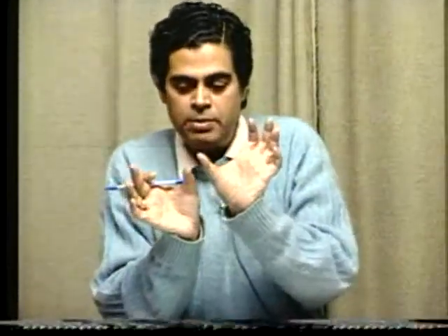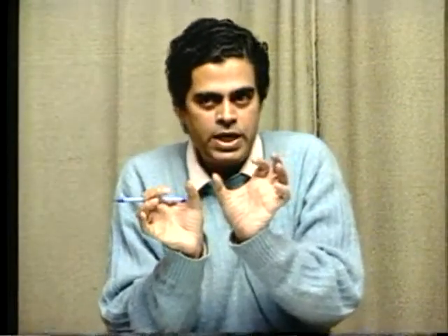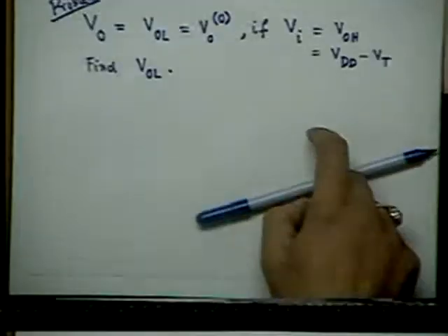How to determine the boundary between the values of VI and VO around which, in one equation, I have assumed that the driver transistor is in saturation, and in the other equation I have assumed the driver transistor is in linear region. So there must be some border between the two. And what is the corresponding VI and VO value?